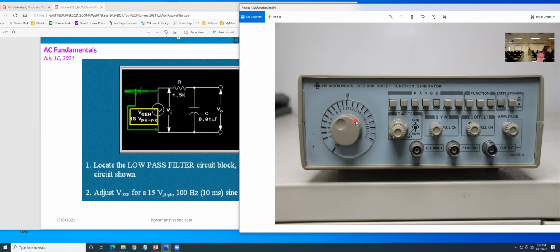Okay, that means right now you display the signal sideways in the oscilloscope. And then on channel 1 of the oscilloscope, you set it to display frequency. Then you can change this here until your oscilloscope says 100 hertz.